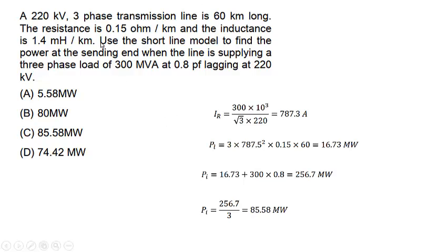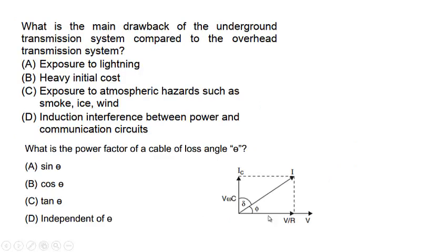So actually it has asked to find the power at sending end. It has not mentioned the single phase power. But the options are in the single phase power, so you need to divide by 3 to get 85.58 megawatts. One more question, which is very simple question.